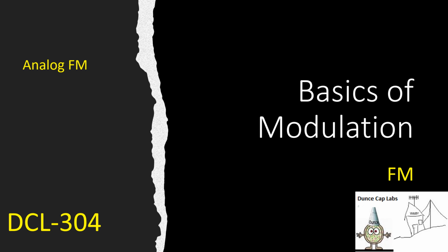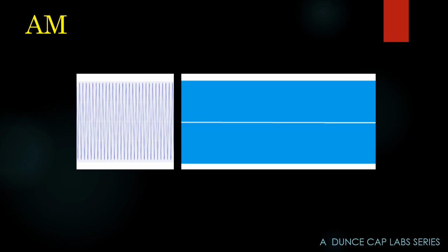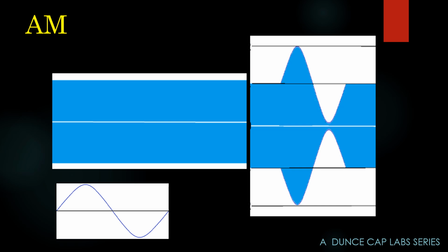digital voice modes. Let's start by taking a very quick look at AM. You remember AM, sine wave carrier. So high in frequency, we don't even care about the individual sine waves. We take our low frequency audio test tone, and to superimpose it on the carrier, we use the amplitude and phase of the audio signal to vary the power level of the RF carrier.